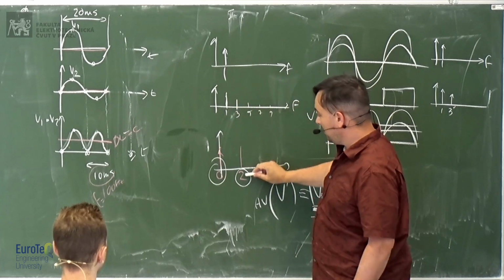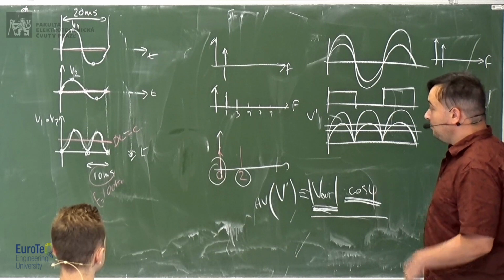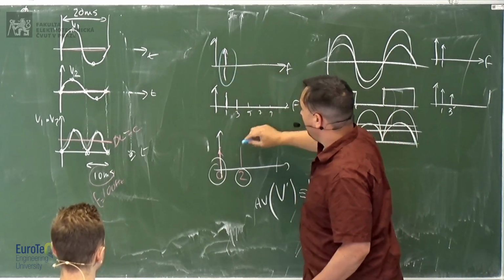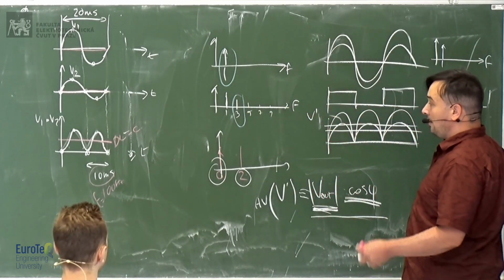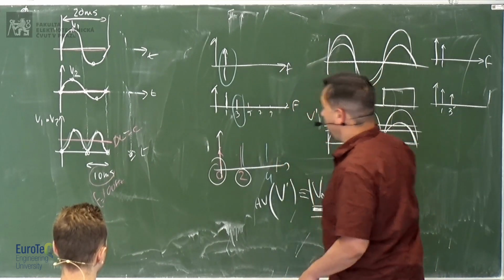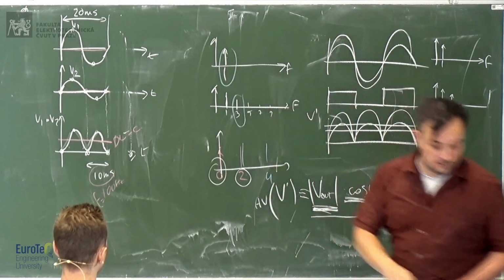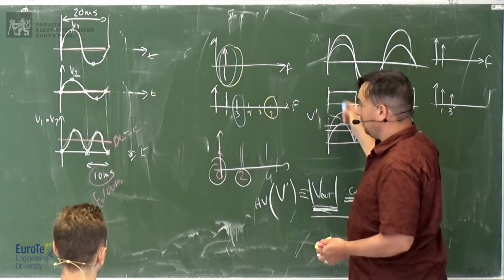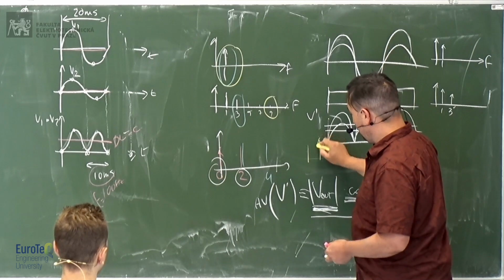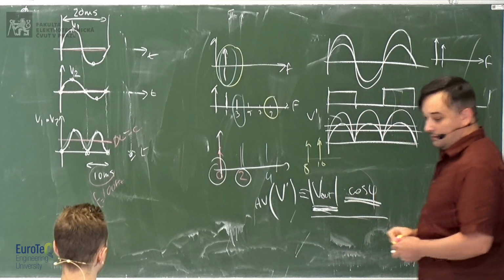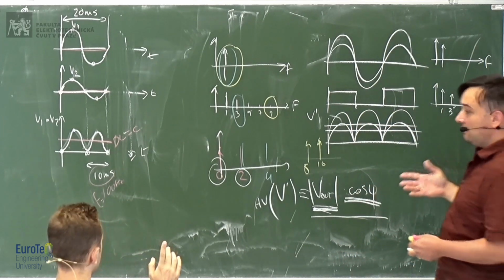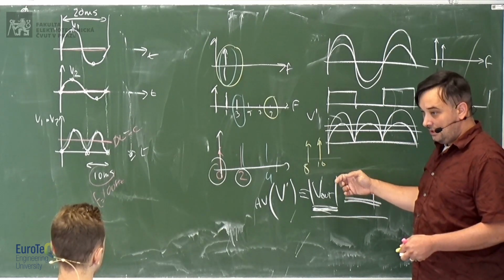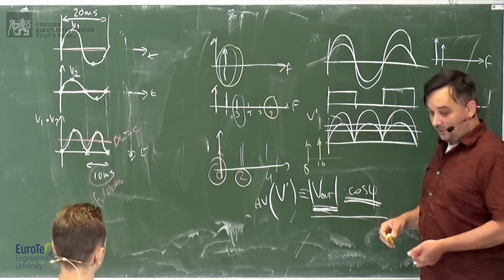So if you multiply 50 Hz times 50 Hz, you get 100 Hz and 0, okay? And you do it for everything. So if you have now 1, the first harmonic, and the third, you will have 2 and 4, okay? 2 and 4. 1 and 9. You have to make all the combinations, okay? 1 and 9. It will be 10 and 8. The sum and the difference. Correct? Confused? Every time you multiply two frequencies, you have in the output a frequency component corresponding to the sum of the frequencies, and a frequency component corresponding to the difference of the frequencies.